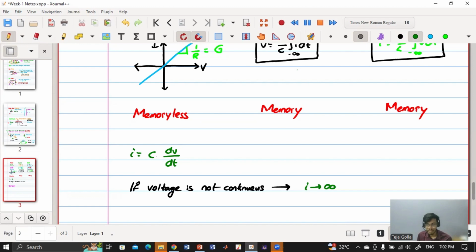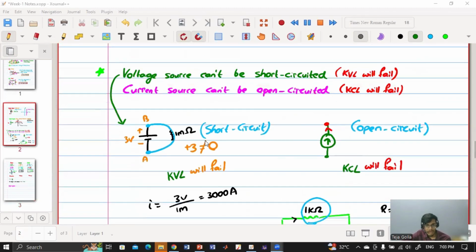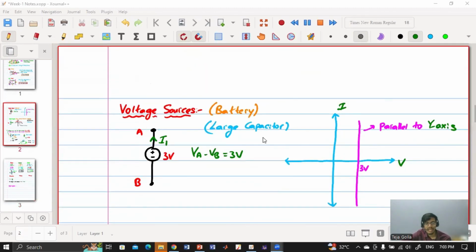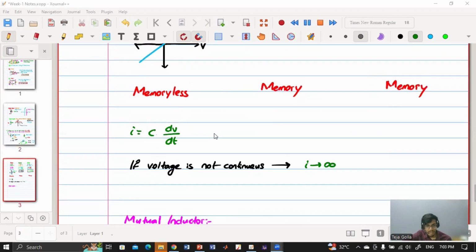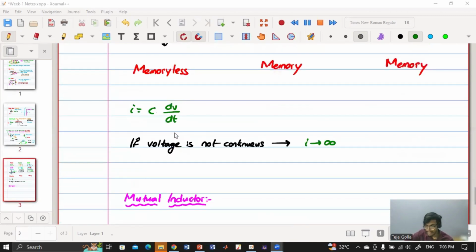At this moment it cannot be 2 volt, and in the next moment 5 volt. So it will change smoothly; continuously the voltage has to change. Now, if I consider one large capacitor bank, its ability to change immediately will reduce. If I add more and more capacitors, the voltage will be more stable. So if I want a voltage source, I will consider a large capacitor.